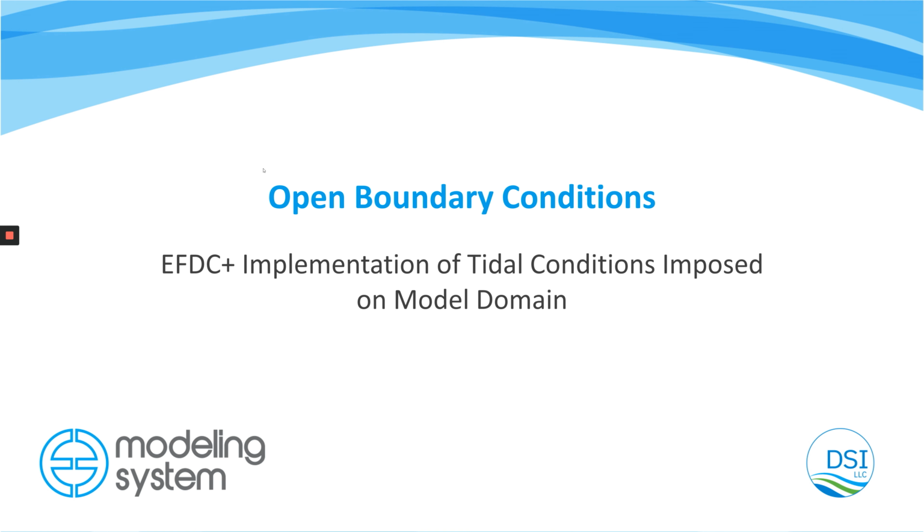You can get jets of water that seem to appear out of nowhere and have Froude numbers on the order of critical flow in a very deep open ocean area, and that makes no sense. That's not something that happens in nature. So depending on how you set up these open boundaries, you can get some pretty bad results. What's important is to configure them properly and know the different things that you need to do in order to make these open boundaries behave realistically.